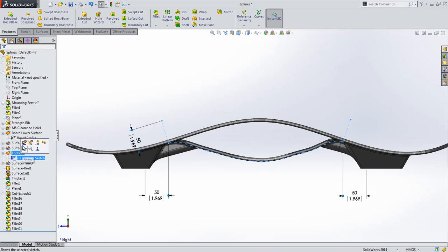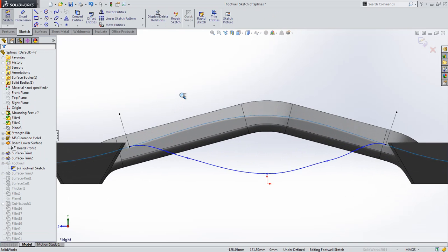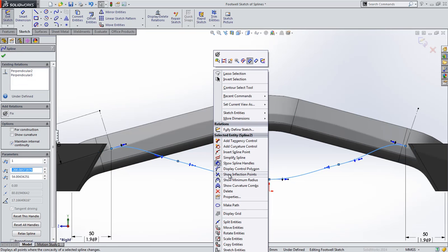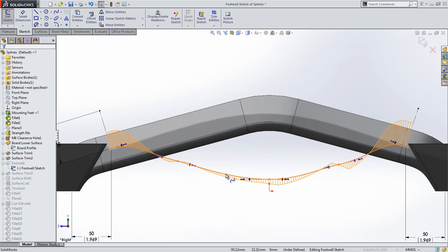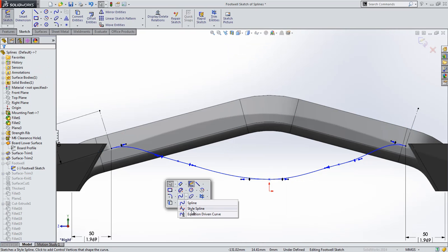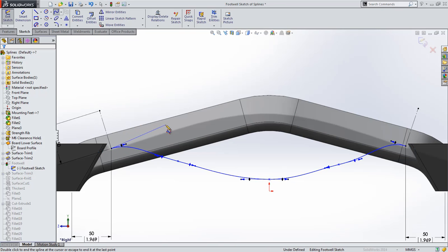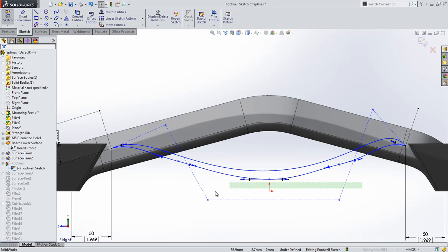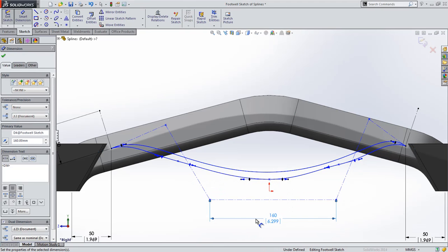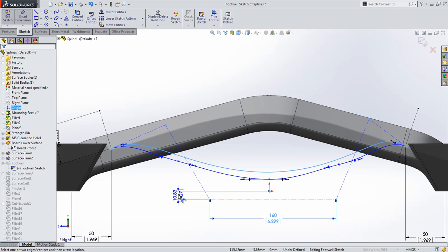Finally, while we're talking about splines, sometimes, especially for new users, they can be intimidating trying to get all the geometry just right. Controlling the inflection and maintaining a smooth profile require proper definition of spline points, such as this spline here. SolidWorks 2014 introduces a completely new spline tool that removes all of these concerns, called the Style Spline. Instead of individual spline points, which need to have the curvature and magnitude controlled, they are simply placed with construction lines. These lines can then be further defined using simple and familiar sketch relationships and dimensions all users are familiar with.